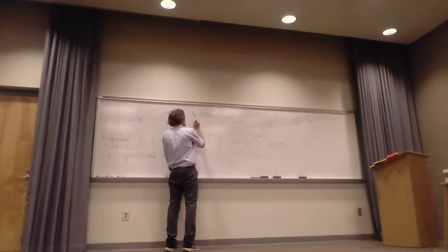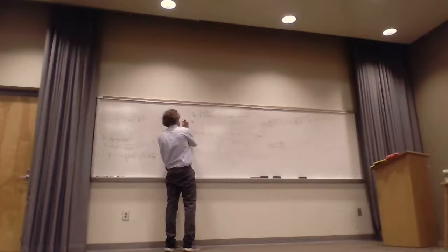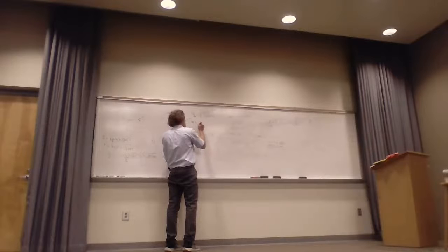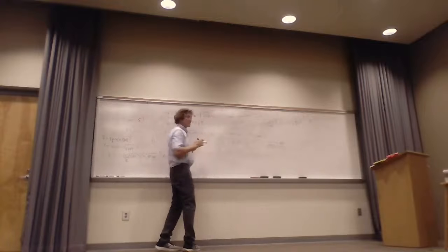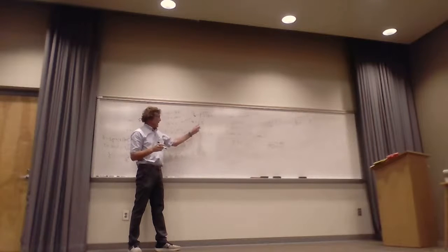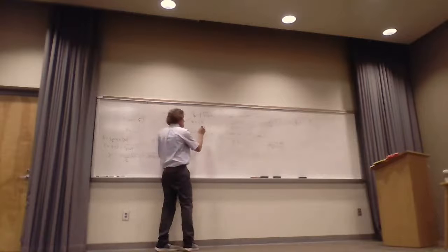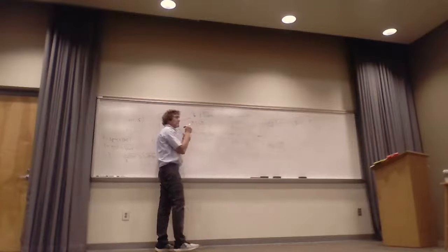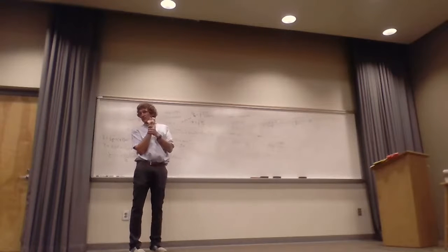So if we assume sigma is much, much less than omega epsilon, eta is about equal to the square root of mu over epsilon, since the j's and omegas cancel. Here mu naught is 4 pi times 10 to the minus 7th, and epsilon naught is 1 over 36 pi times 10 to the minus 9th, right?